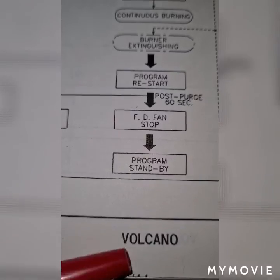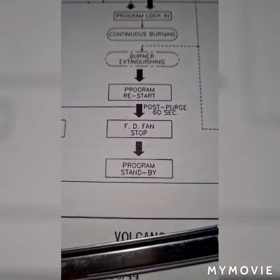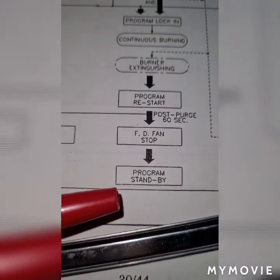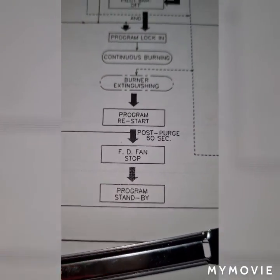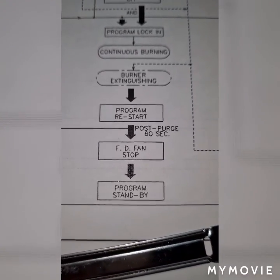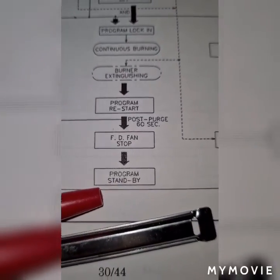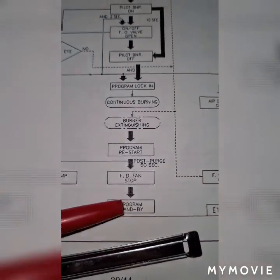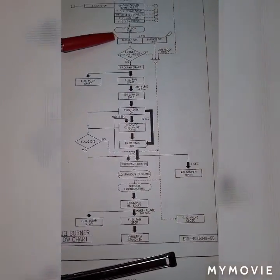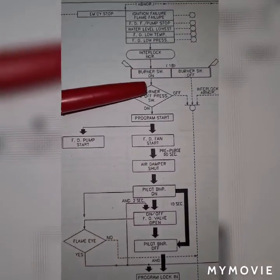On the standby mode, it will wait until the pressure drops to about 0.47 to 0.49 megapascal, and then the boiler will automatically start again from the beginning.